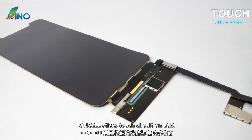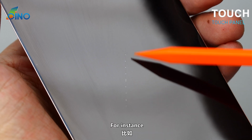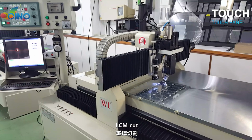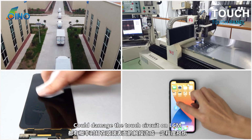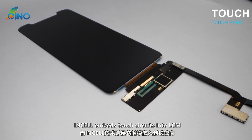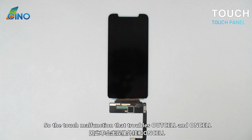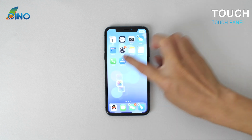On-cell sticks the touch circuit on the LCM. The exposed TP is fragile. For instance, cleaning with alcohol, transport, and LCM cutting, these necessary steps for later installation, could damage the touch circuit on the LCM, thus hurting touch function. In-cell embeds touch circuits into the LCM. There is no independent TP on in-cell, so the touch malfunction that troubles out-cell and on-cell will not haunt in-cell.